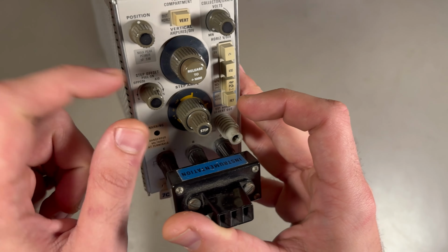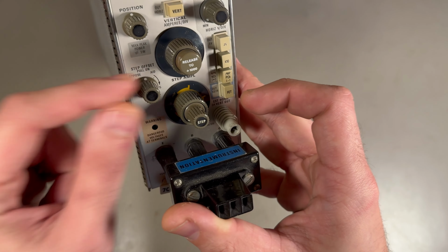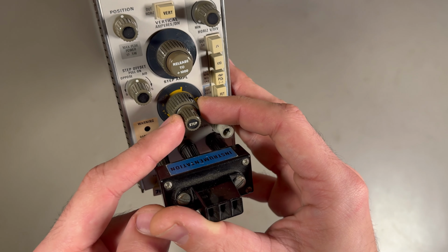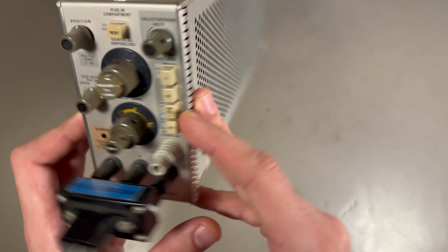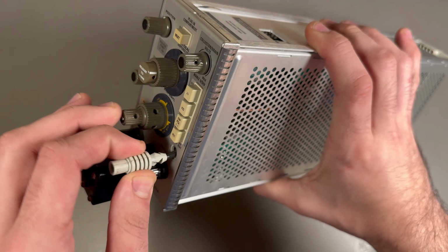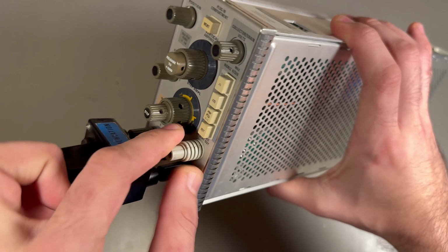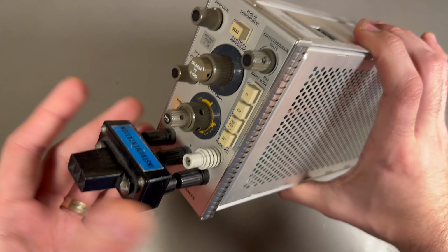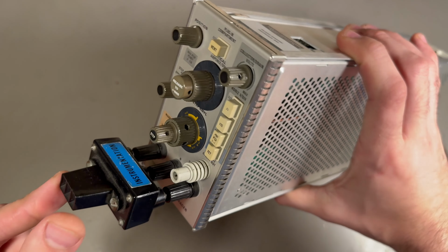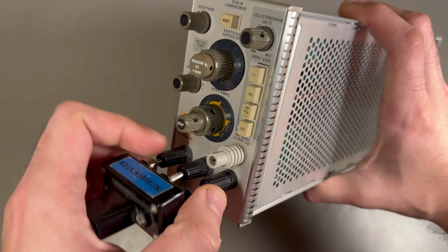You pull it to enable it, you push it to disable it, and this is to aid or oppose the step generator. So it actually contributes positively or negatively against the step generator. This is that BNC that I was telling you about. You're meant to take this out from the unit and plug it into a nearby vertical on the front of the oscilloscope. And these are the main connections to the device under test.